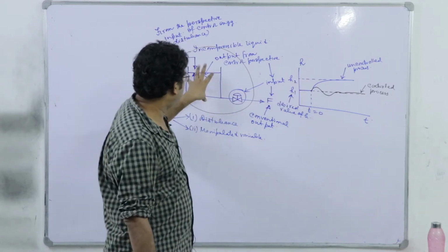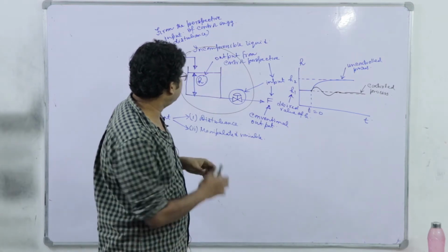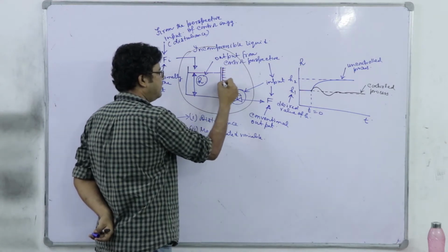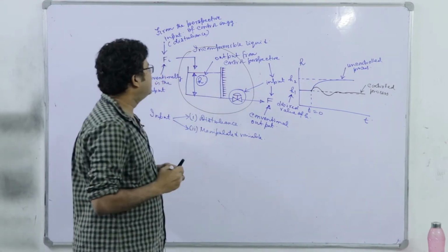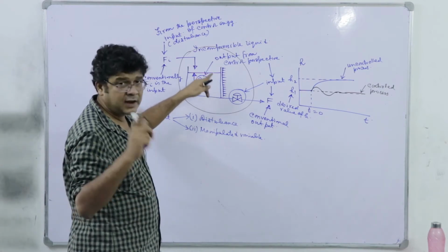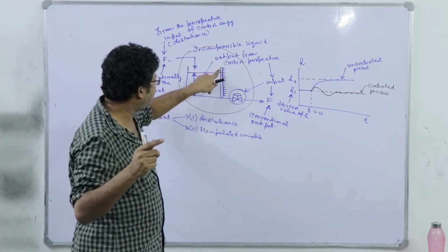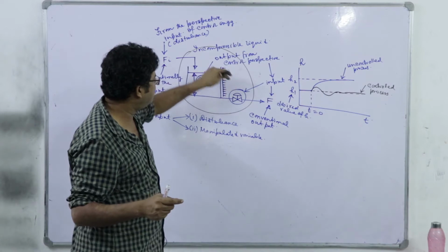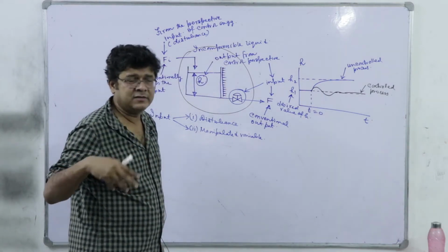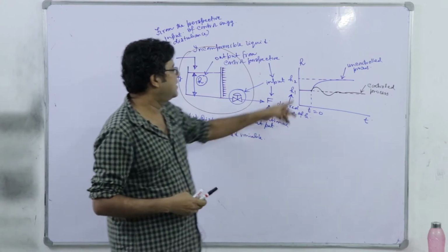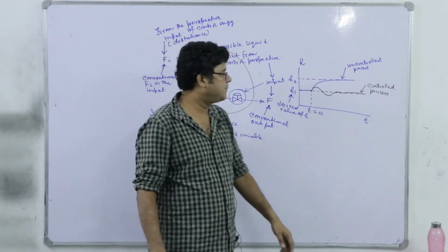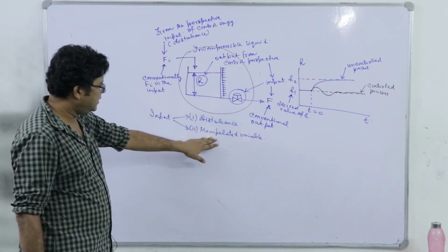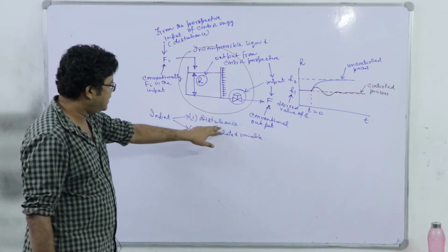Once there is a disturbance, we observe that it's changing, there may be some level gauge or a manual scale fitted on the side. So we note that reading. I am trying to operate this manually. I note that reading, and immediately I see that the level is increasing. I am not measuring Fi, so I will open this valve. So I adjust it based on my experience, I go on adjusting it, and finally the level will settle down again to H1.